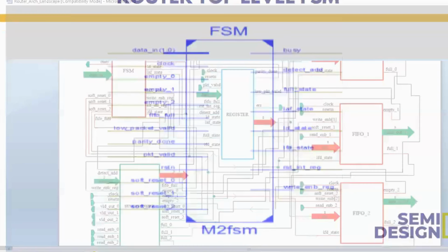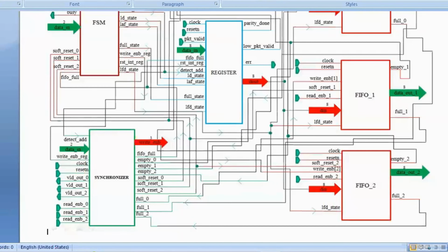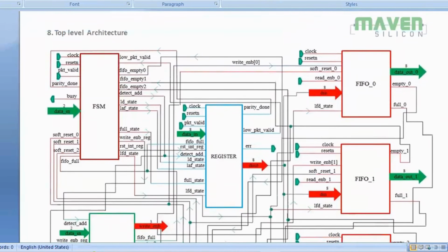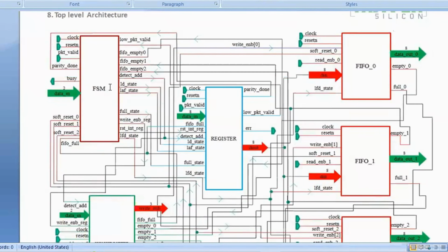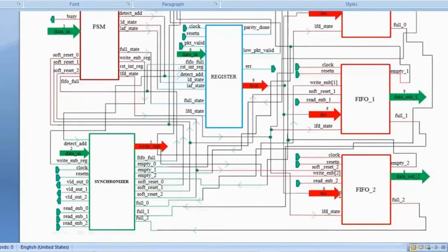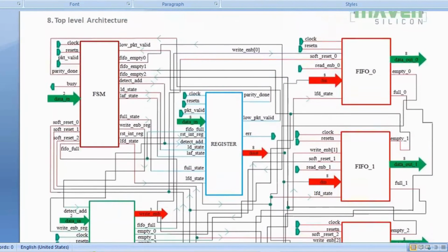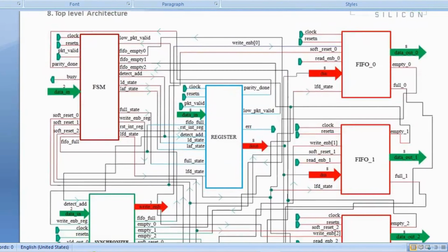You can see the block diagram here. This is a little more clearly visible than the previous one. So 00 in FSM will select this FIFO, 01 will select this, and 10 will select the third FIFO. 11 will be invalid. So maybe we can assume that there is no transfer happening. We can keep that for an idle state.